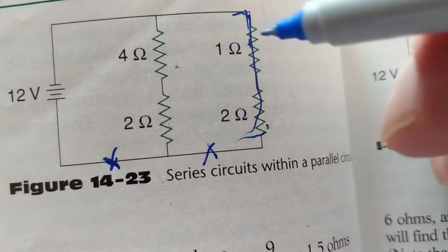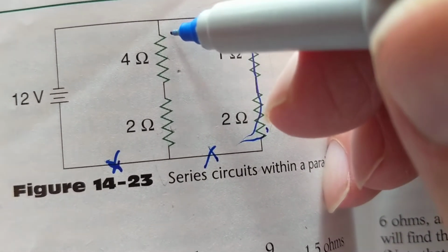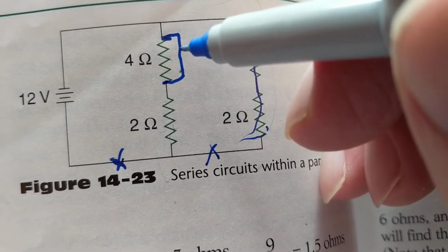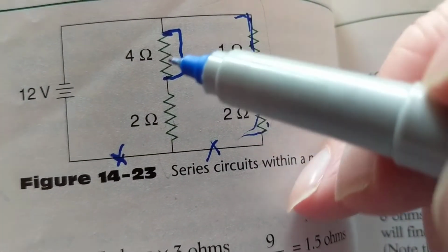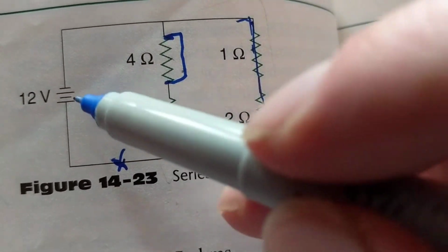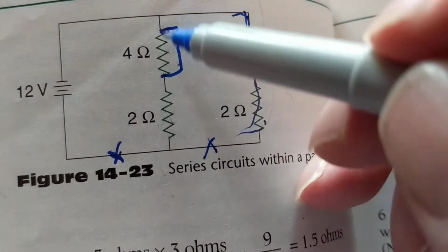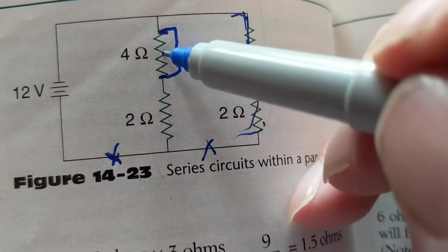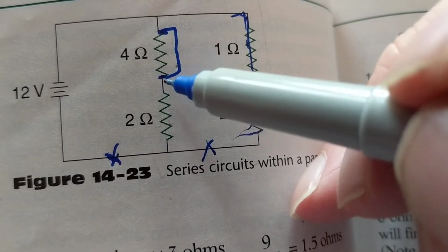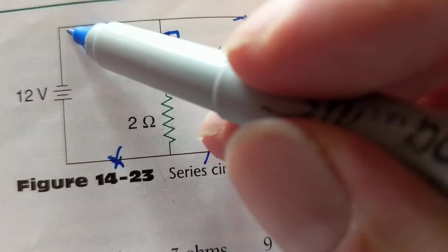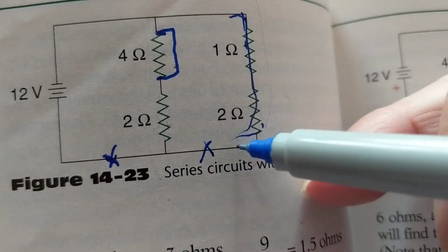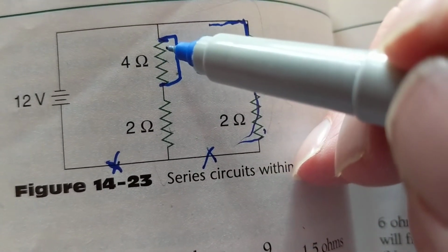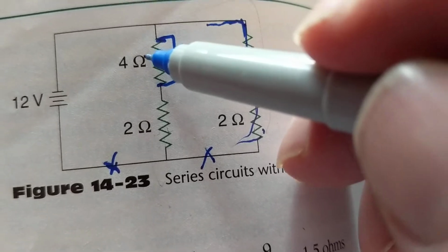We have a short. Let's create a short, then we're going to go to one more. We have a short across this one. This is a short. Can current still flow? Current can still flow. Why? Because it still has a complete path to go back in this branch. Branch here, a branch here. The current can still go, skip over the 4 ohm bulb, go through the 2 ohm bulb, and go through back to the battery. As well as current can still go over here, back to the battery. It can still go. Like I said, the resistance will change. 4 ohms is out of the picture.